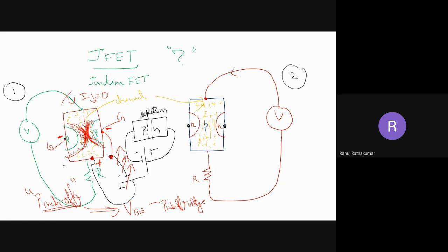Okay. Now the same will come to the P channel JFET. So what about the P channel? Right now there is a good current flow here. Current is easily passing through. Now in the N region I have to give a positive voltage for reverse bias. So in these two N regions, I have to give a positive bias with respect to the P region, so I'll connect it to a battery source like this, plus and minus.